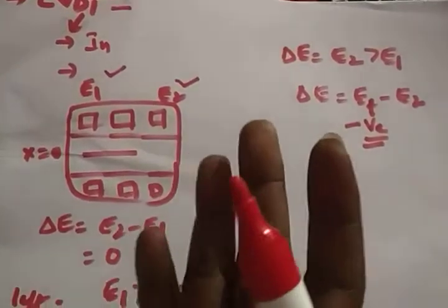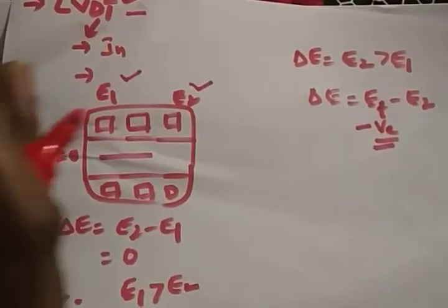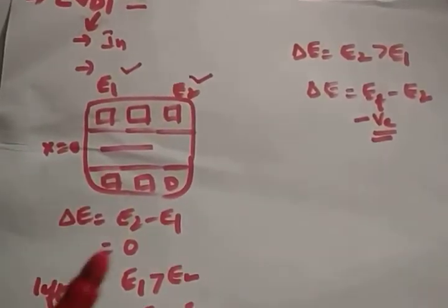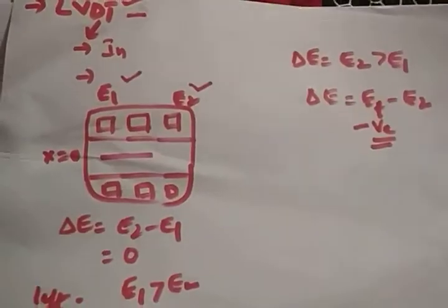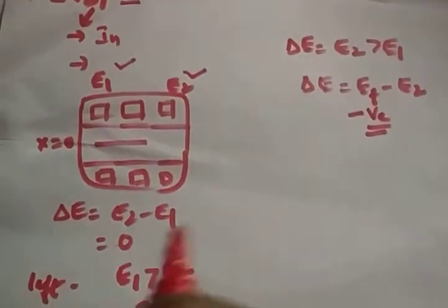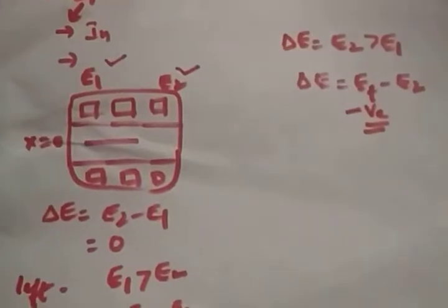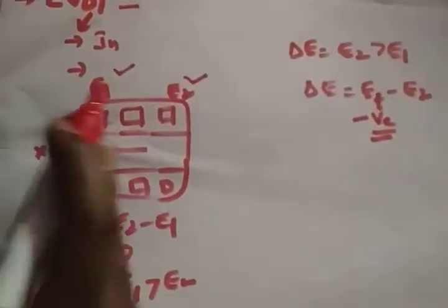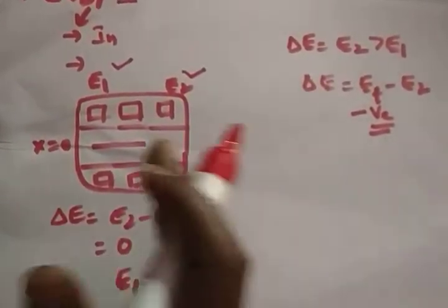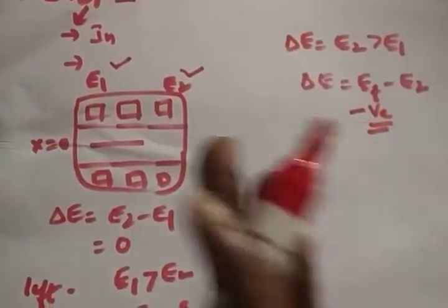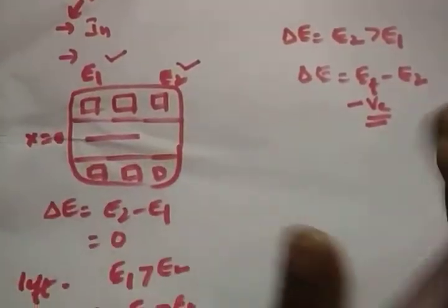How do you get this change in voltage? By varying your displacement. Definitely your displacement is converted to voltage, so it's like a transducer. How does the displacement vary? You are varying it linearly, not rotationally, not up and down. You are linearly varying your soft iron piece.